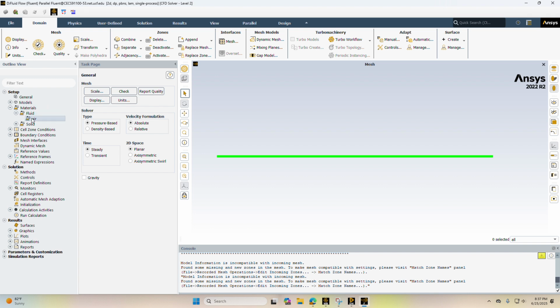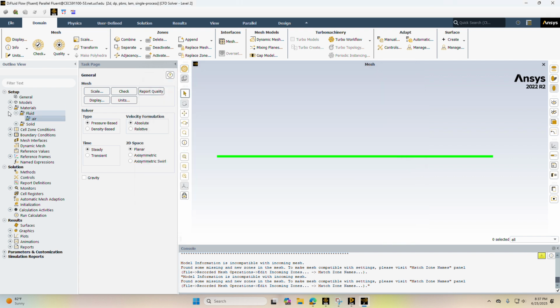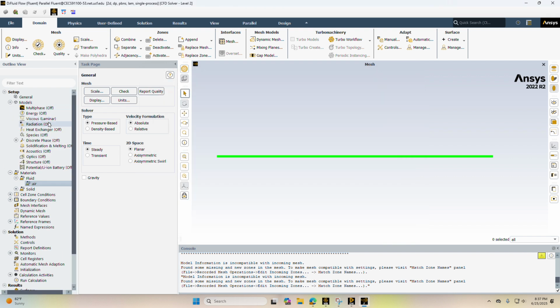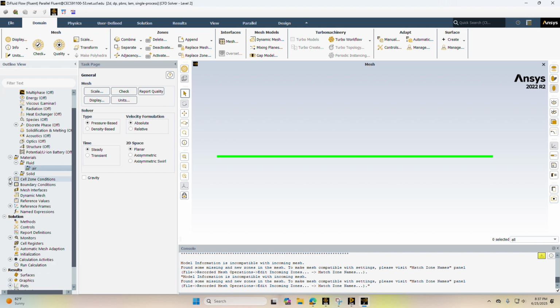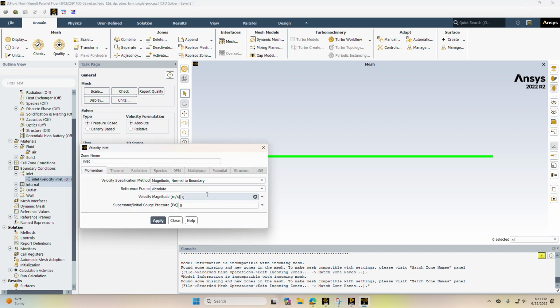Let's make sure our fluid is proper, yes. And our model is laminar. Okay, now we can mess with the boundary conditions. Here, our inlet is, we want to manipulate the velocity. The one I chose and worked best for me was 10 meters per second.